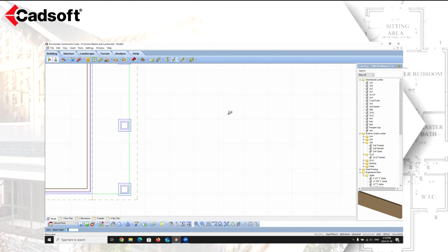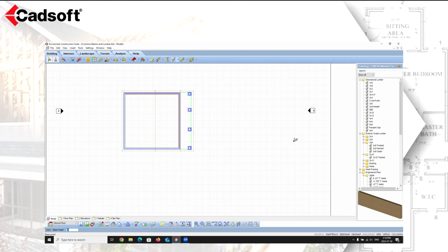We're now going to select a member, and we're going to bring it into our design. So let's grab a member, and let's insert a member in our design here. So let's grab a 2x8 member, and I'm just going to bring my mouse in. I'm going to left click once, and now attached to my cursor is that member, and I'm going to move it left, right, up, or down, and it's going to start from where I selected, and I can move my mouse in any direction.